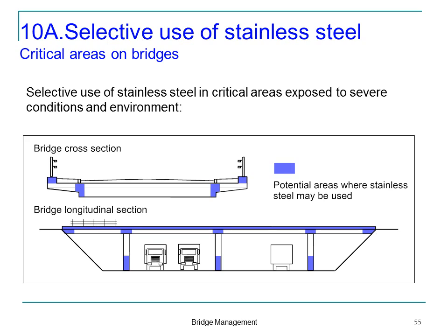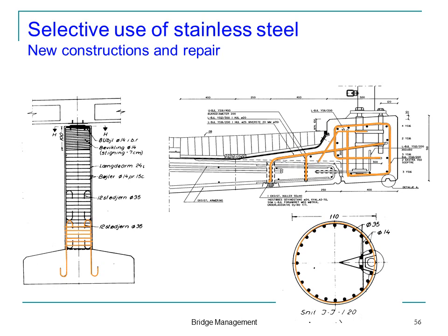Same in the superstructure, we know the cross beam and this beam, these places are very sensitive. Well, use stainless steel there. And even sometimes take the bottom here, say, well, no. The column reinforcement, that will still be ordinary steel. Well, the stirrups, well, that could be stainless steel. Obviously, the salt that penetrates into the reinforced concrete from the outside will reach the stirrups first. So make these in stainless steel and these in ordinary steel, and you have probably gained 20 years of service life.